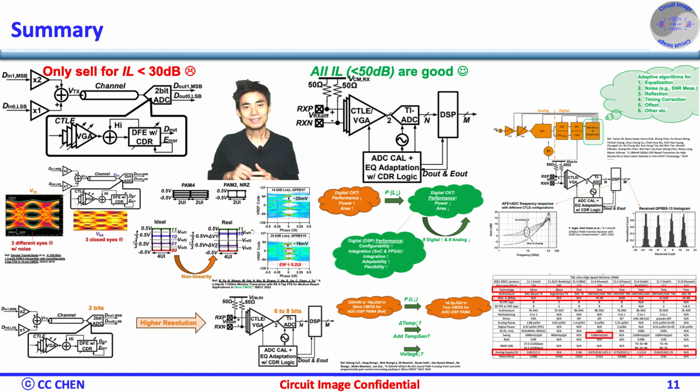Then, second, the ADC DSP PAM4 RX not only can tolerate more input DJ, SJ, RJ, noise, ISI, reflection, nonlinear input, etc. external impairments, but also provide a good integration with SoC, FPGA, and test scalability in the most advanced technology, which improves the PPA a lot. Third, the ADC DSP PAM4 RX would be easier in the debugging and testing owing to all the available internal error behaviors through the DSP.